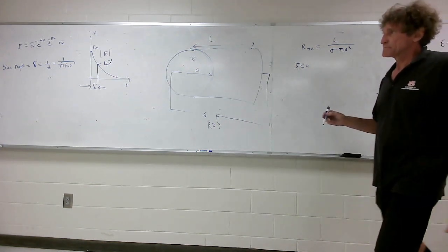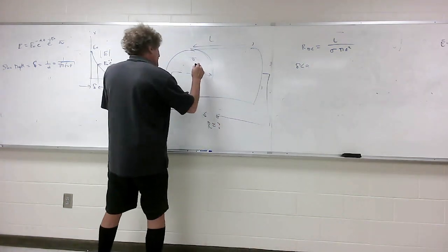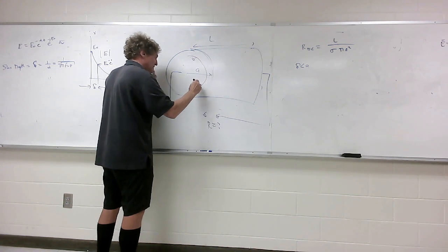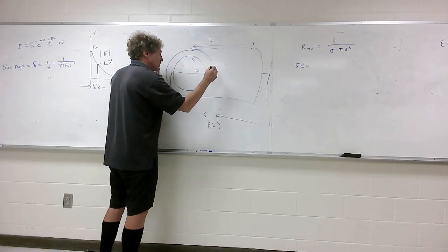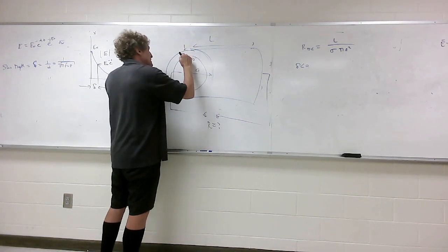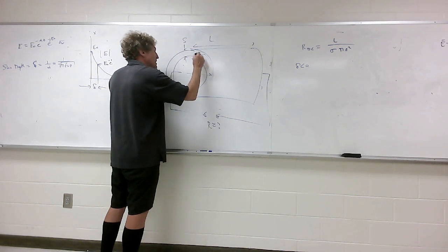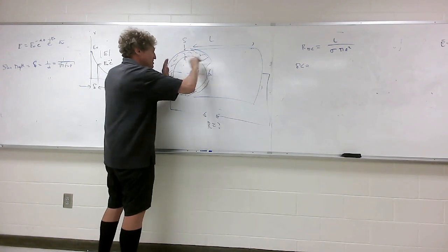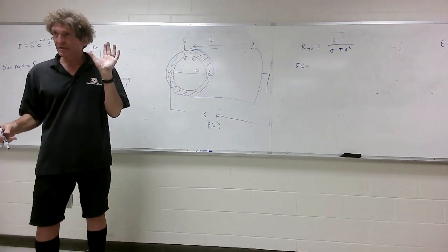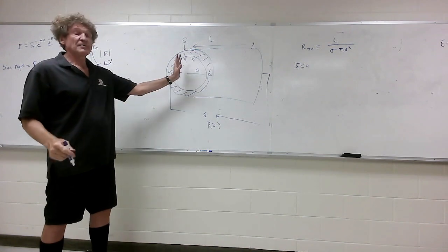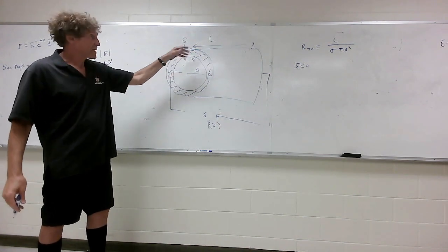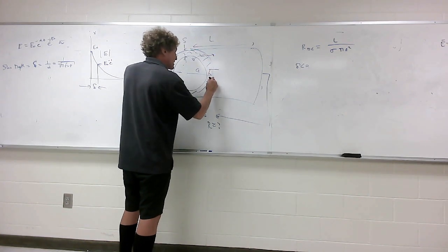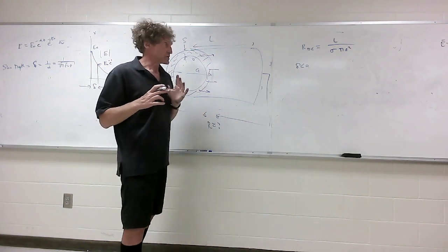So what it's saying is this. If I could make you imagine this, I'm not going to do a good job. If this region here is one skin depth, all the current flowing in this wire will just flow on this outer wrapper, one skin depth in thickness. It will not flow inside. That's just what happens. The wave will decay too quick. So we assume all the current is flowing in this hollow cylinder, you might say.